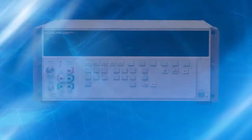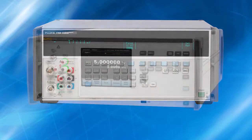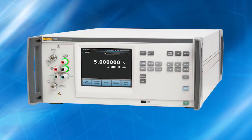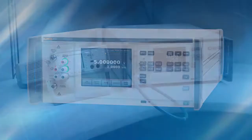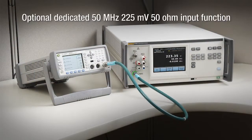The 5790B has a 5790A emulation mode, so you can replace an existing 5790A by just swapping in the new unit. A dedicated special purpose 50 MHz, 225 mV, 50 ohm input function is available as an option for measuring RF power. The option is spot calibrated at the end of a precision, level, or phase stable metrology grade cable. It calculates the measured power with 50 ohm load.